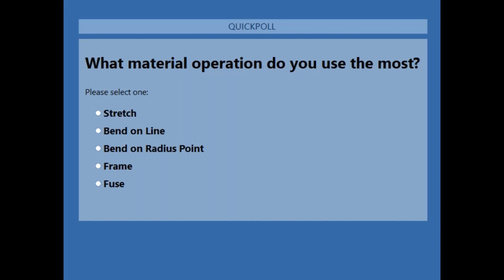I did turn to dark mode the last session that we just had, so everything has now changed. But yeah, we do have the forms up here, or it was in my settings as well. If I come into my project settings and then plugin defaults, member plugin defaults, and then handrail, you can set up all your defaults in there.